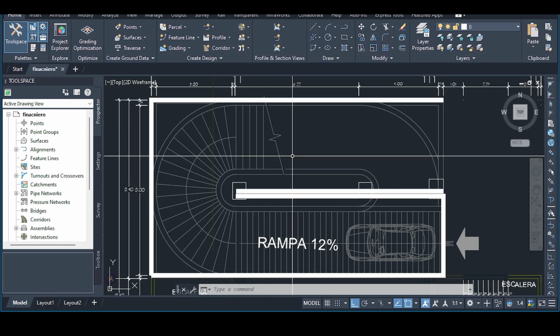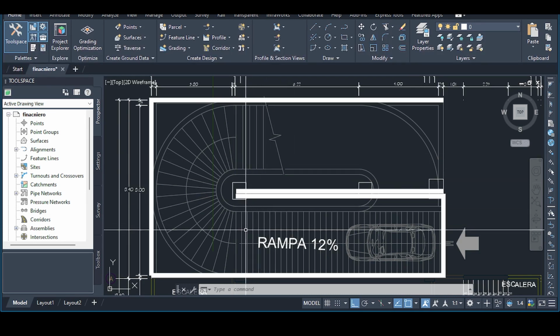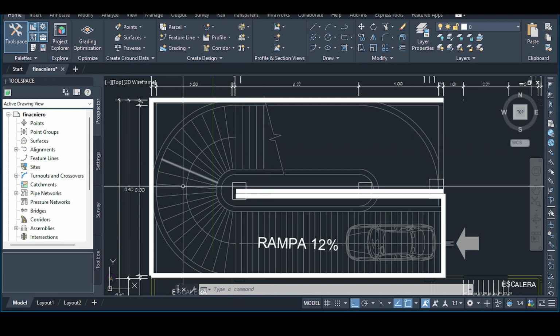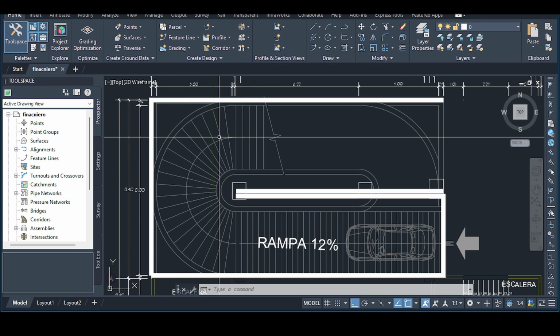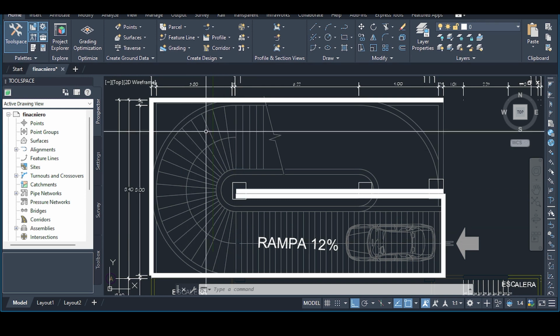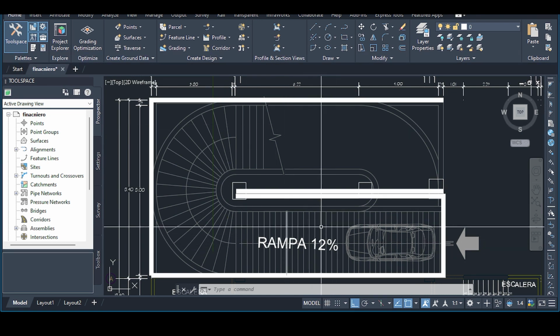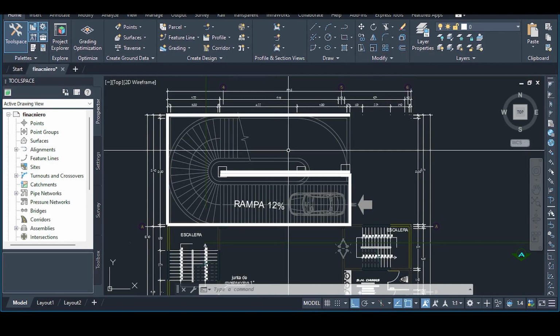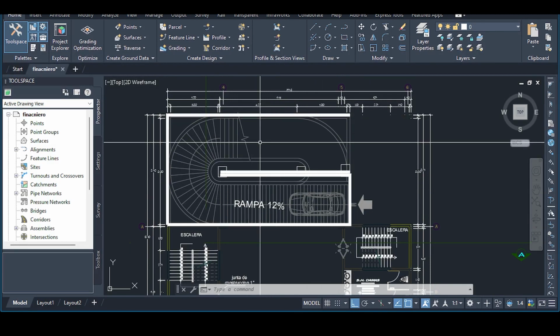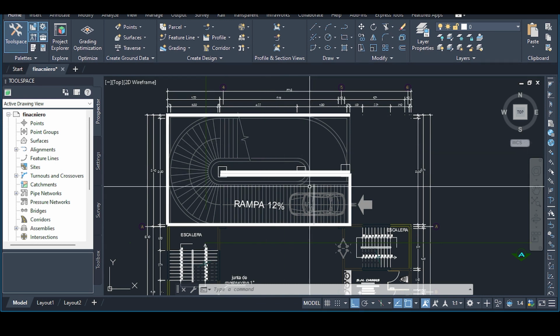Allow me to explain. Of course, the advantage of the spiral, meaning that the curve here is not horizontal, is first of all, it looks cool. Well, that's a good thing, actually. And the second thing is that if you have a spiral, then your slope decreases. Because what is the slope of the ramp? The slope of the ramp is the height difference divided by the length of the ramp. And by the length, I mean the sloping length.